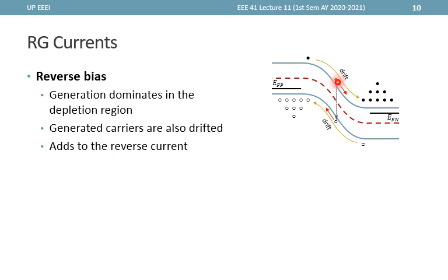This electron drifting to the right provides additional current going to the left, or in the reverse direction from N to P. So there is some additional reverse bias current, meaning if we plot the diode IV curve, this is our expected curve, focusing on the reverse bias case.